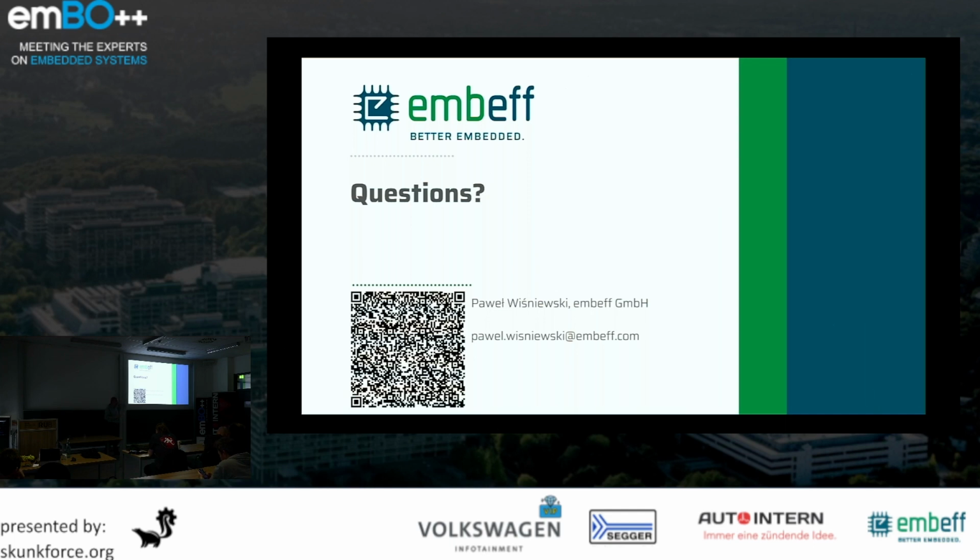We are focusing at this moment on the single components because this would be a good starting point. Then you have some data that you can work with, because now with the tools that are there that I saw, you just calculate something, put 20% on top, and then this is how it works. So now you can get some real data, and this is the first step. The other one, you need to observe it. I think then tracing would be something like this. You need to put a trace on a real system, stimulate some inputs, outputs, and all the stuff, and then evaluate the trace at the end to look if there were some deadlocks or some deadline misses and so on. This is a different kind of testing, one level higher, I would say.